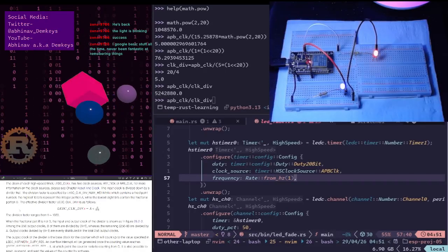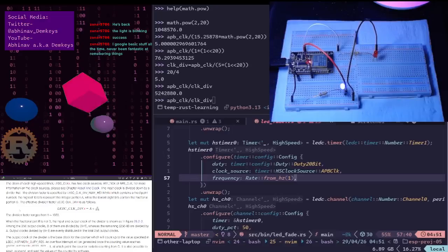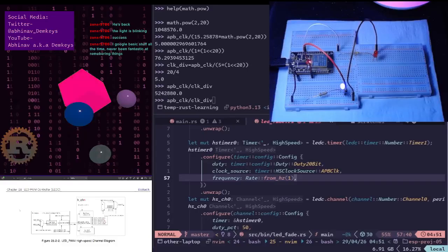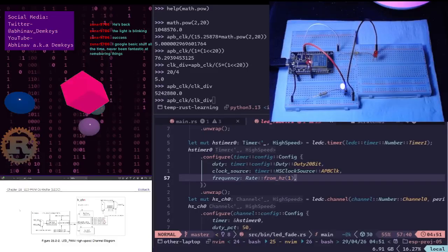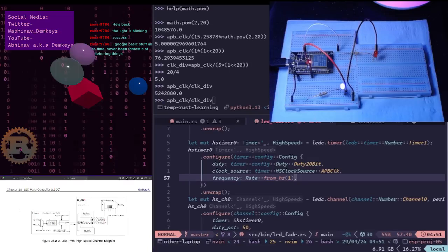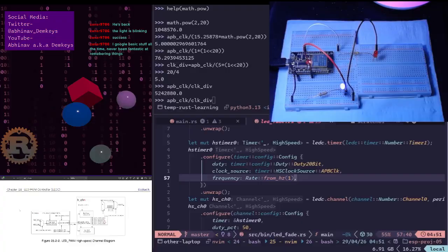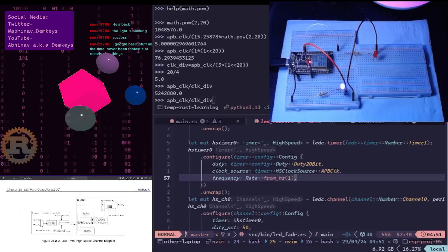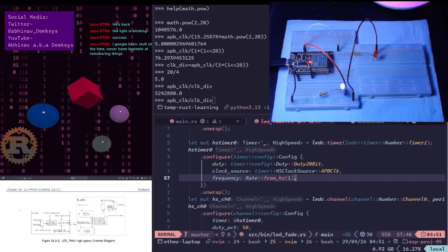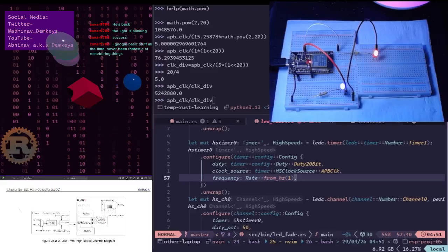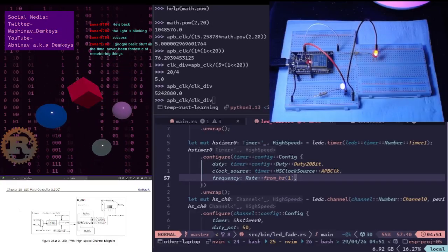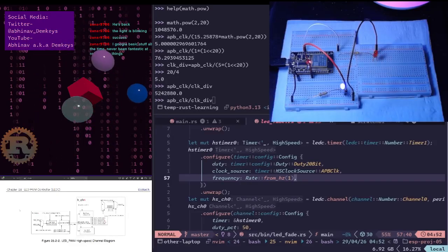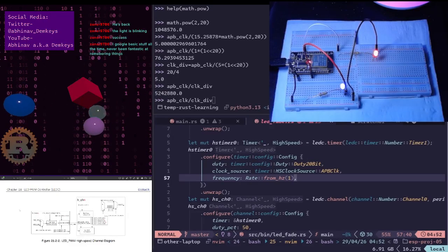So internally in the fractional divider, that's what it's called, we also have a counter that's constantly counting the number of ticks that have passed, and its target value is basically whatever we have decided the fractional divider to be. Okay, now I'm getting it.